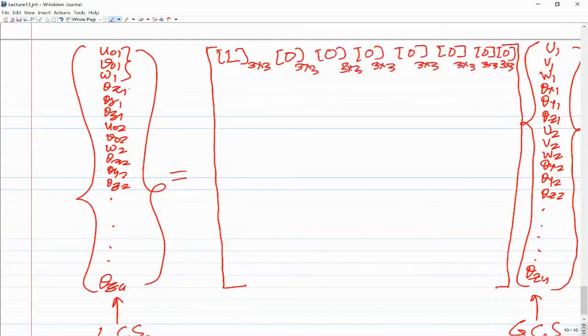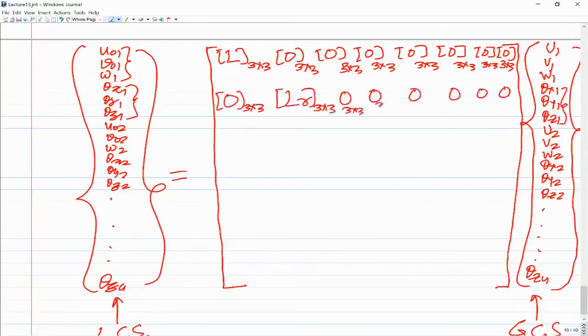Then next, if you look at this theta x1, theta y1, and theta z1, those can be written in terms of these three. So you will write here first a null matrix which would be 3 by 3, and then you will bring in LR over here. LR is also 3 by 3, and then you will have the zeros. All the zeros are 3 by 3. So essentially you can understand that all these have to be 3 by 3, and you will construct this transformation matrix.